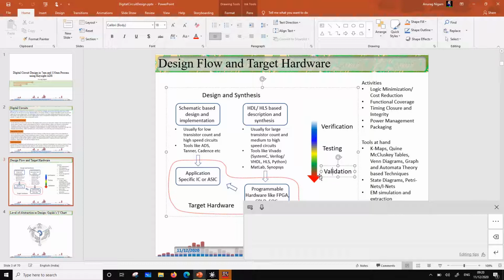And what these programmable hardwares are, these are usually lookup tables. So in an FPGA, for example, there are no gates actually. There are lookup tables, and these lookup tables are stored in registers. And then there is a memory element like a flip-flop, and then there are multiplexers and demultiplexers to design any combinational circuit. So these 3 elements are used to make what is called programmable logic, or it's also called a CLB, a configurable logic block, which can be used to implement a functionality.